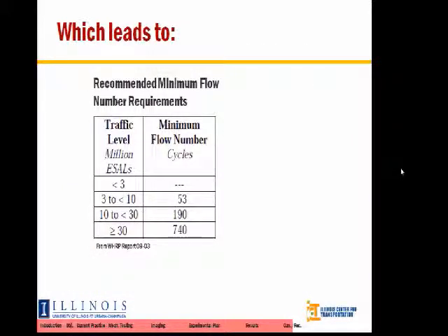How can we begin to implement this? There have been previous studies, in this case, a Wisconsin Highway Research Program study. I believe this one was conducted by Ray Bonaquist, which several people in the room or viewing should certainly recognize the name. He had conducted a lot of work on flow number testing and ended up trying to suggest or recommend a minimum flow number based on your anticipated traffic load or your ESALs.